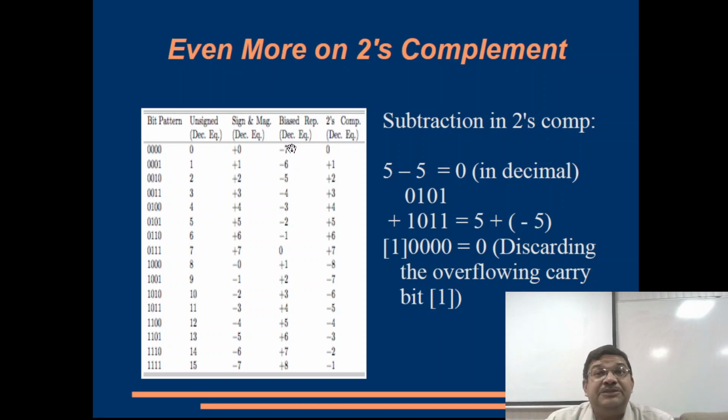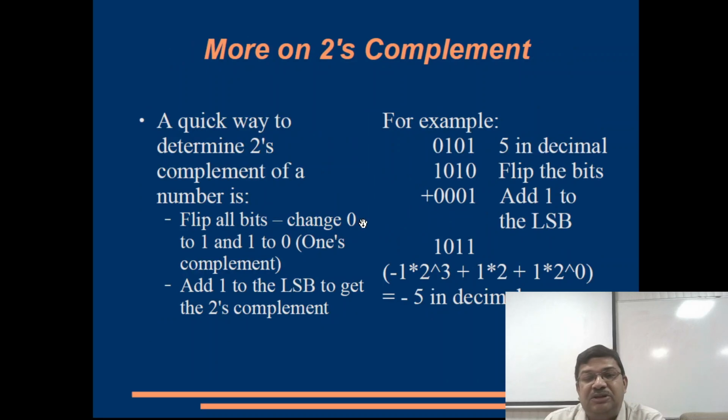Then, yes, 1011. Which one? No. Why should it represent minus 3? The 1 is not for the sign, it's not that. It is this: 1 and the weight is negative. For the most significant bit, the position value is negative. That is how it gets its sign. So don't confuse it with sign and modulus form, right?